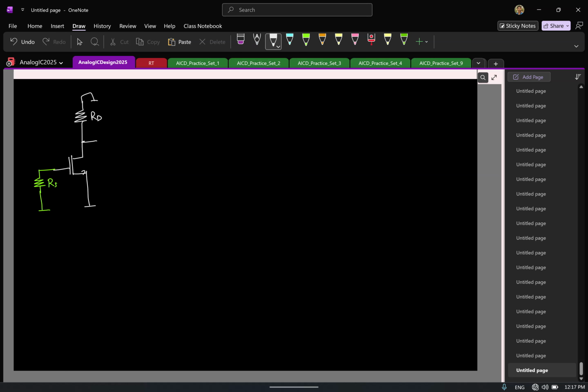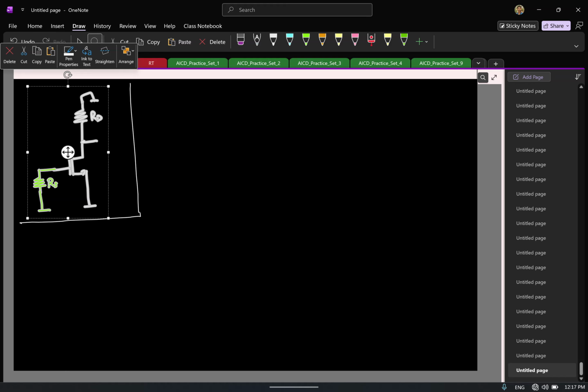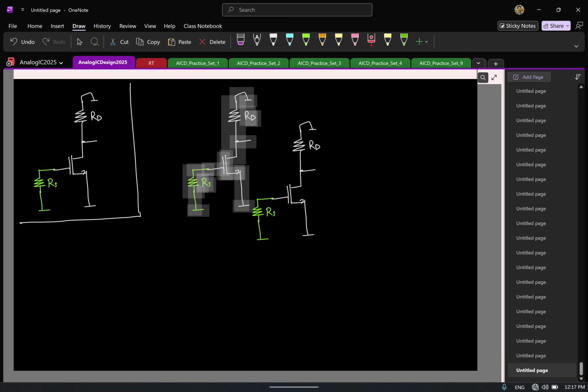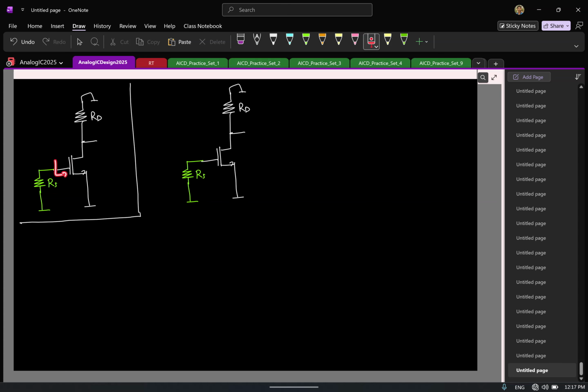So now my goal is the following. I want to make sure that I'm able to capture the noise in the network. First of all, let me redraw this. Tell me, what is the input impedance of the network? Infinity. So do you think I need to find both voltage and current? What is sufficient? Voltage is sufficient. But if I actually go and try to calculate the current, what will it become equal to? It will come out to 0. So for the first calculation, we'll religiously calculate both voltage and current, and convince ourselves that the current is actually 0. Let's start with finding voltage.